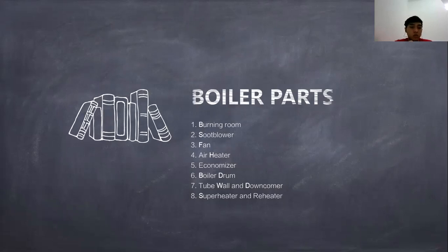Two, soot blower. The function of the soot blower is to clean ash, dust or soot adhering to boiler pipes, superheaters, economizers, and the air heater element. The purpose of the cleaning is to increase heat transfer. The soot blower uses extraction steam for cleaning.